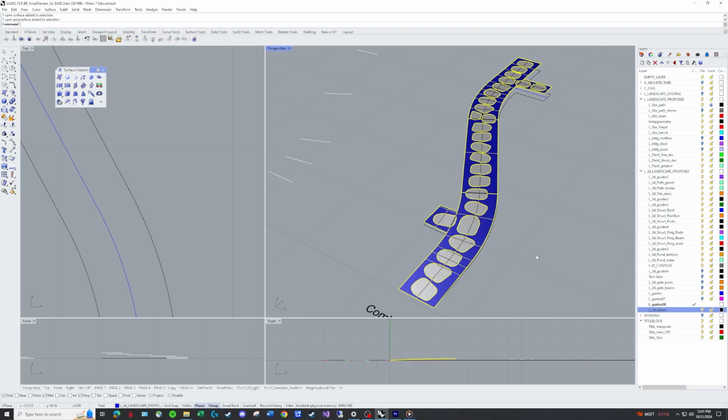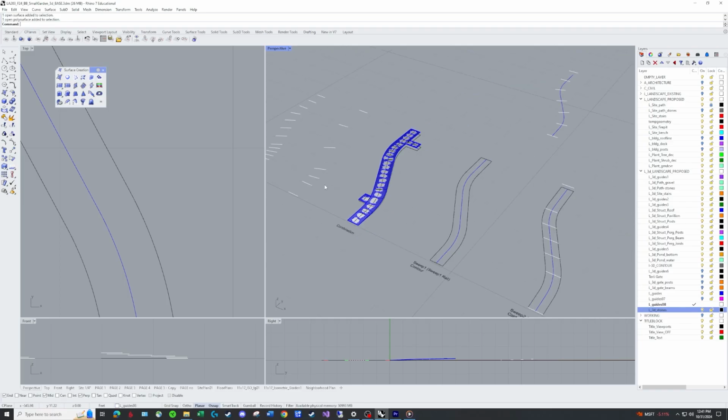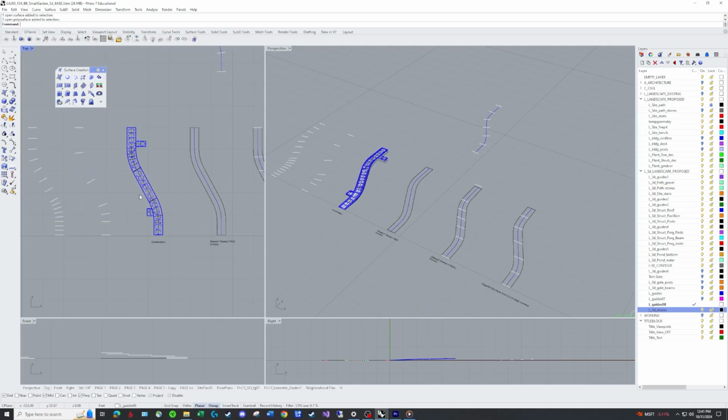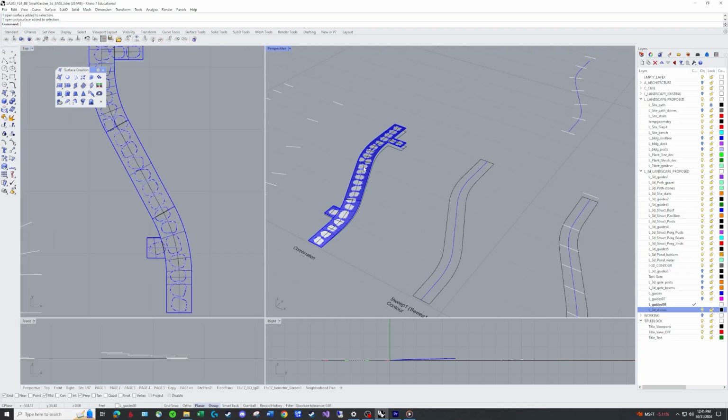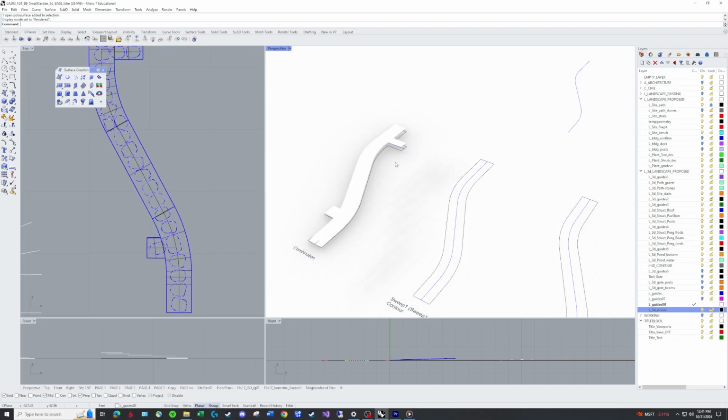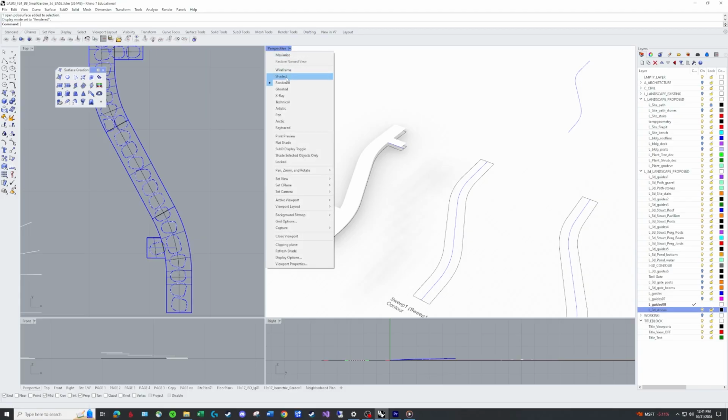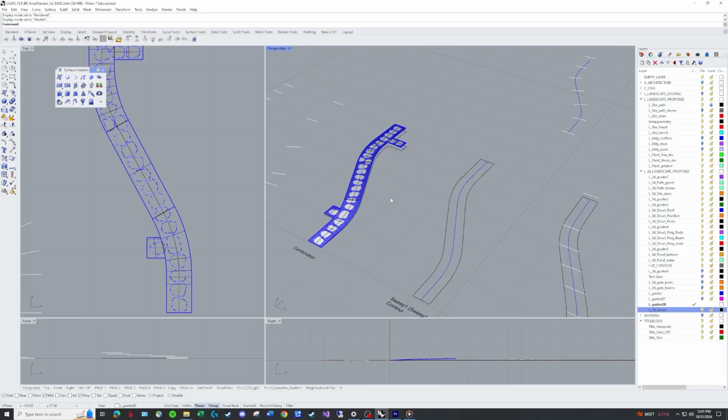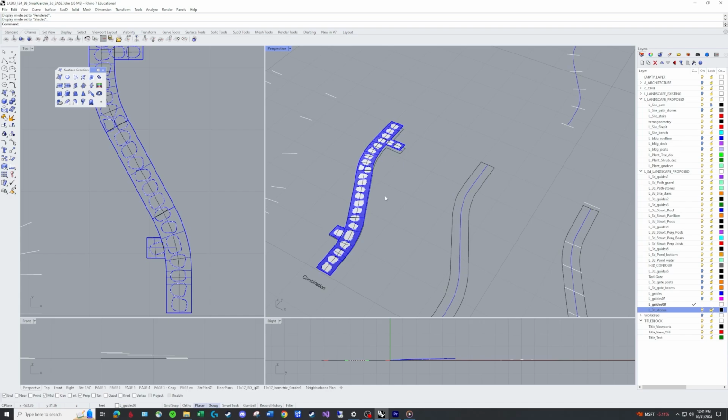We'll deal with the assignment of materials later, but this gives you an understanding of how to construct that. If you render it right now, it's just the same thing. But once we assign materials, you'll see the difference, that Lumion will be able to assign gravel to gravel and stone to stone. And you need to be able to control that, and you do that through the layers.